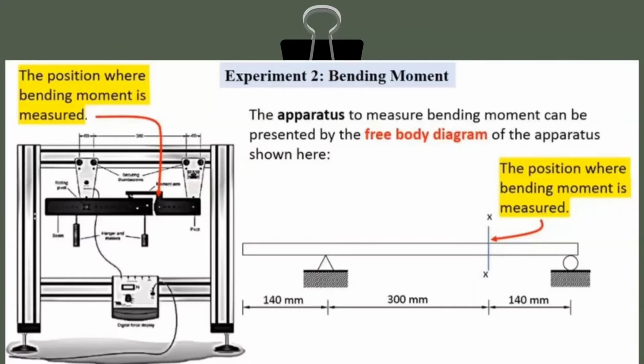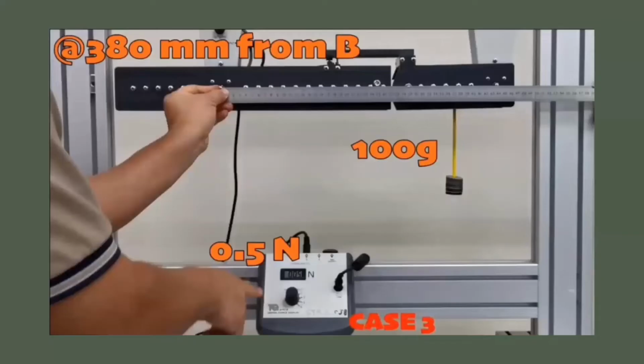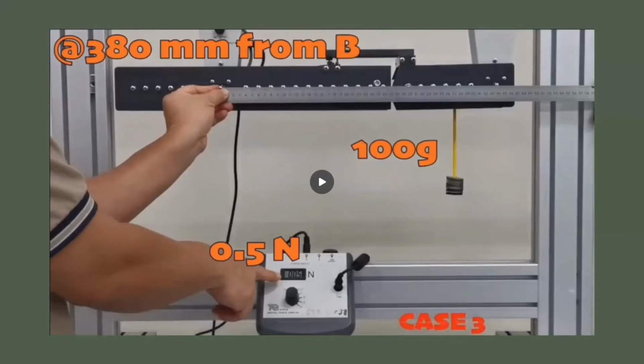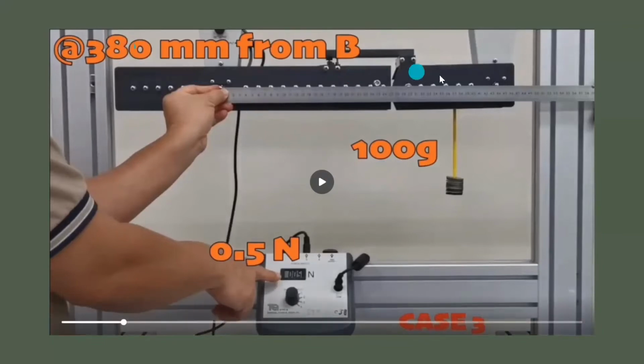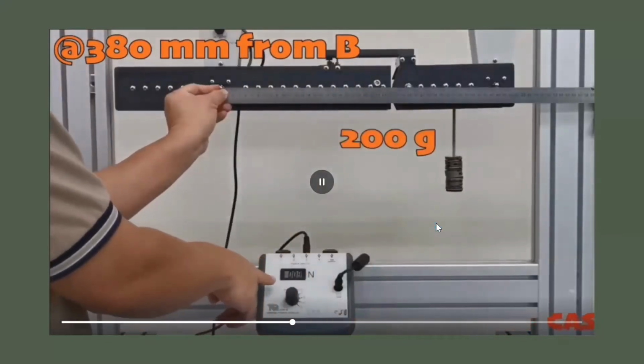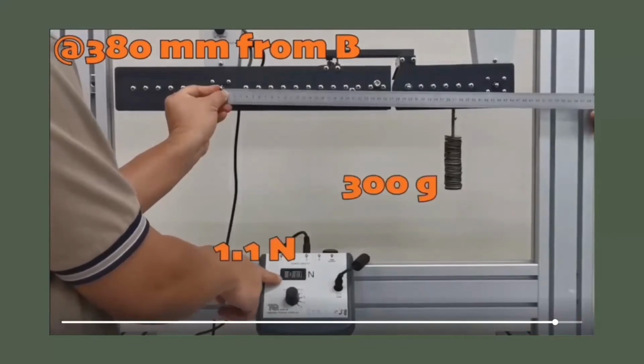This is the free body diagram of our apparatus, and here will be the position where the bending moment will be measured. First is the bending moment due to variation of loads. For the first case, to carry out the experiment, we will measure the distance from B, which is 380 mm, and place the first load, which is 100 gram, and take the reading from the digital force display. We then repeat the same step for each of the loads, 200 gram and 300 gram.